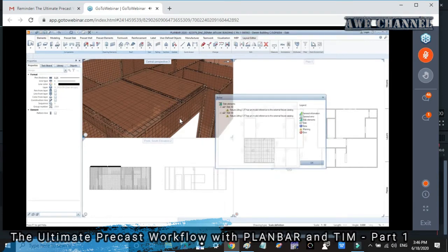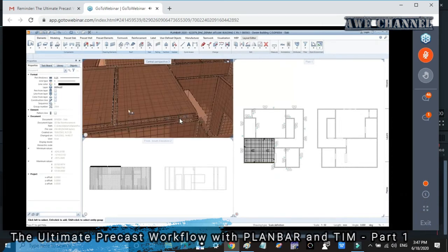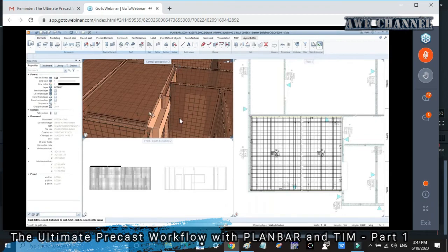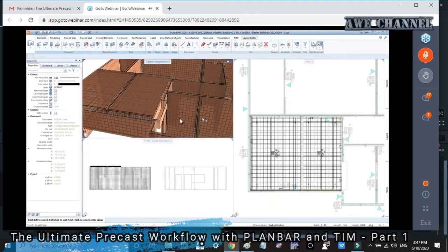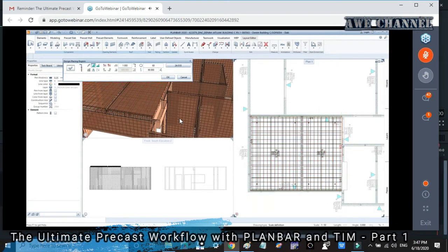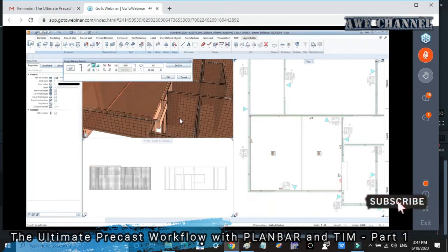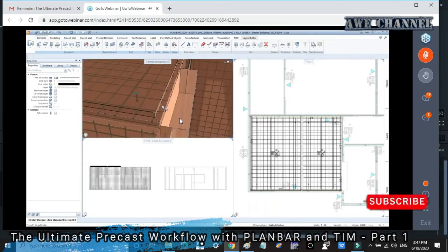For example, connect joints between elements, lifting angle for slab, okay, and reinforcement. And now you can see on this side there is no joint because this is an end face. This is for the wall. If you want to modify it, you just select this side, and from here you can define a joint. And when I say okay, now we have a joint here.